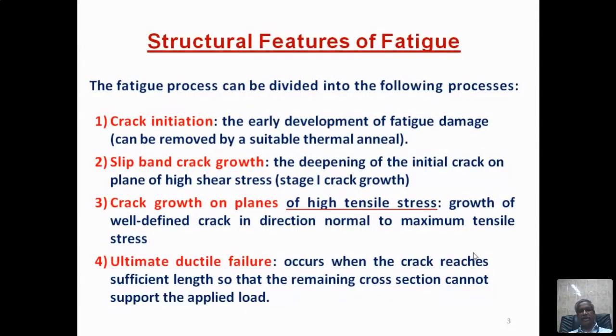The third stage: once the crack is initiated and has started growing to the size of nanometers or micrometers, it will grow on planes of high tensile stress. You can detect it after that even by using a microscope, which can detect micron-sized cracks, even from 1 micron. You can monitor the crack and record the growth of the crack. That's the third stage.